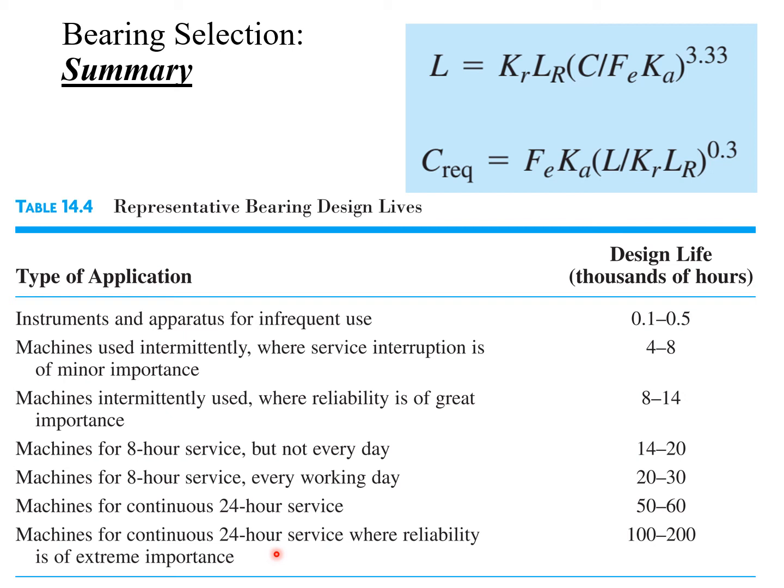So we will multiply times 60 to get to 60,000 revolutions per hour. And then if we multiply times 200,000 hours that we want that thing to operate, that gives 1.2 times 10 to the 10, or roughly 12 billion revolutions that bearing has to endure.